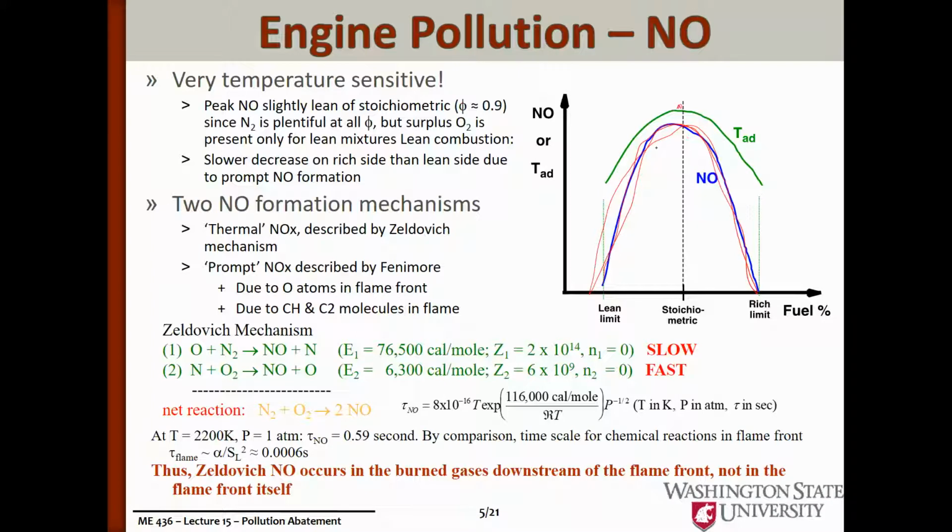There's a significant activation energy to forming nitric oxide because the N2 molecule has to break, and a nitrogen molecule has 3 bonds. So if you want to break a N2 molecule, you're breaking 3 bonds, and that takes a significant amount of energy. So it's really at high flame temperatures where there's significant NO production.